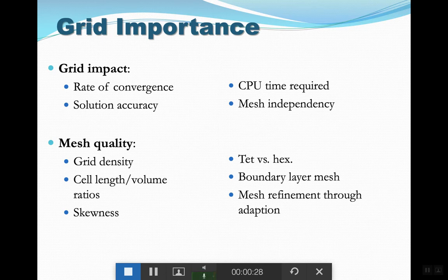So the grid or mesh, a collection of cells, is being used in CFD, and we discussed this previously. It is being used because of the basic assumption that we made when we were developing our Navier-Stokes equation, continuity equation, and the energy equation. And that assumption, if you recall, was that these equations are developed on infinitesimally small differential size control volumes.